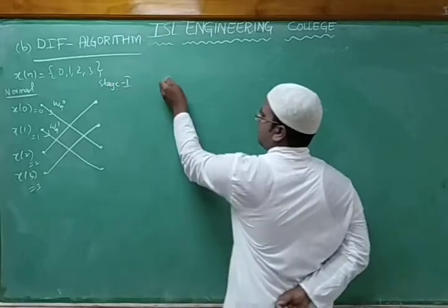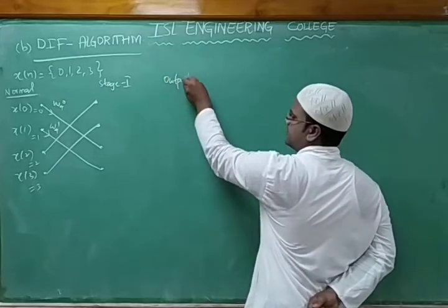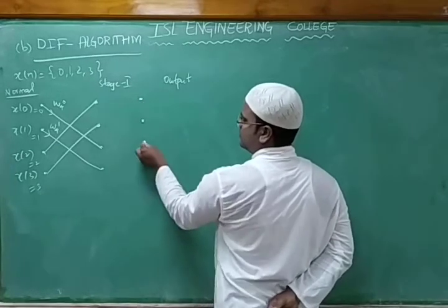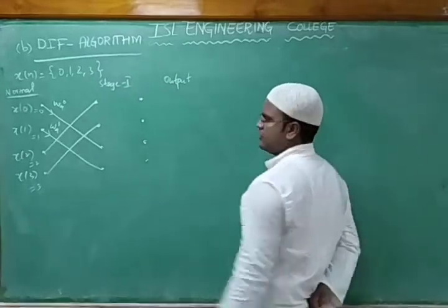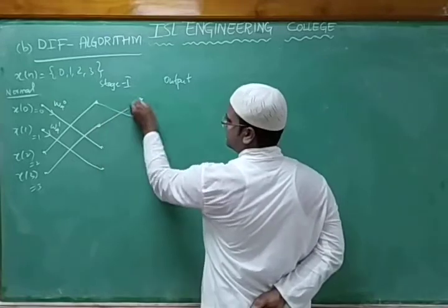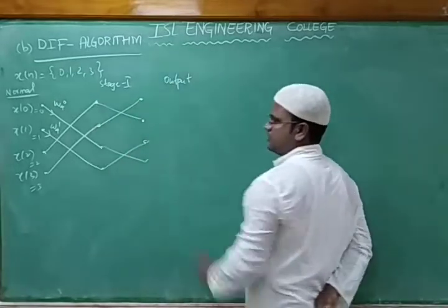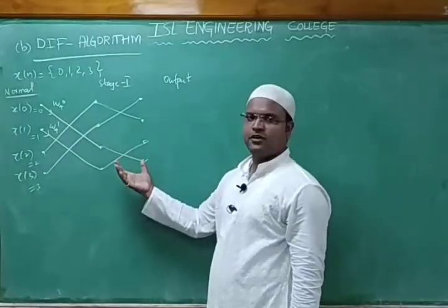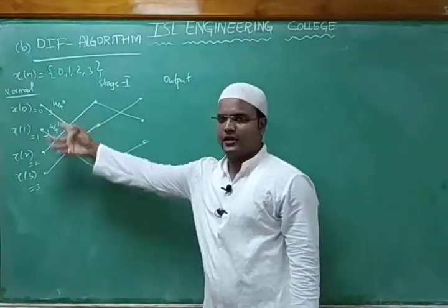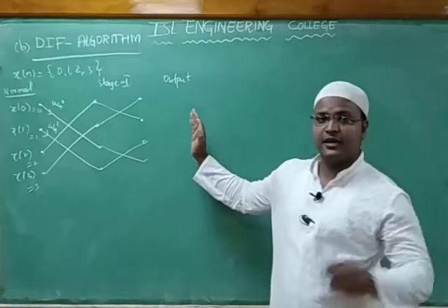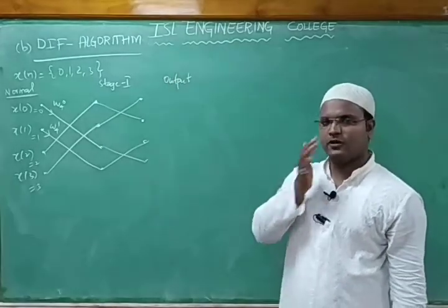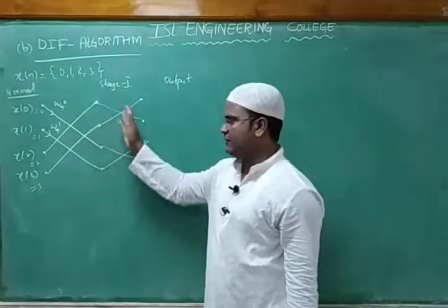Next will be the output stage, that is stage 2. Right? For output what we'll do? We'll put the dots same, 1, 2, 3 and 4. So here directly we'll cross it like this. We will cross it like this. Previously we combined 2, 2. Now here I am combining 4, directly the initial 1 and then 1. It's like a reverse operation of the DIF FFT algorithm.